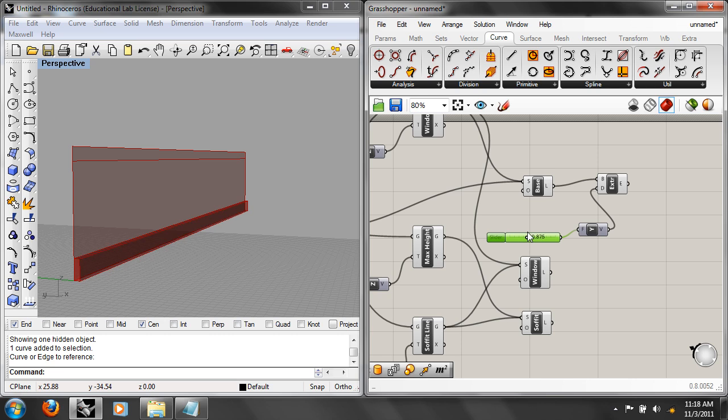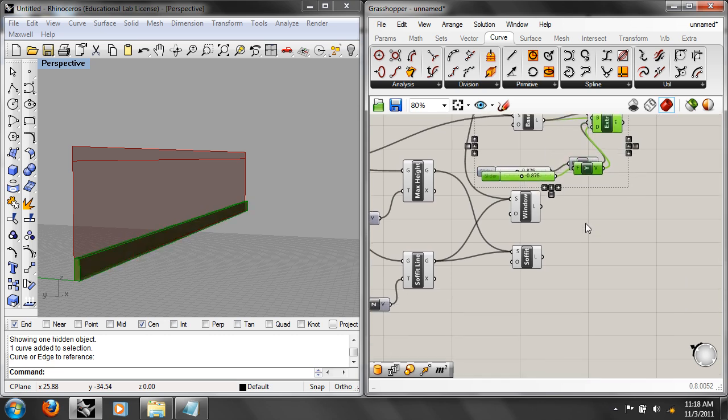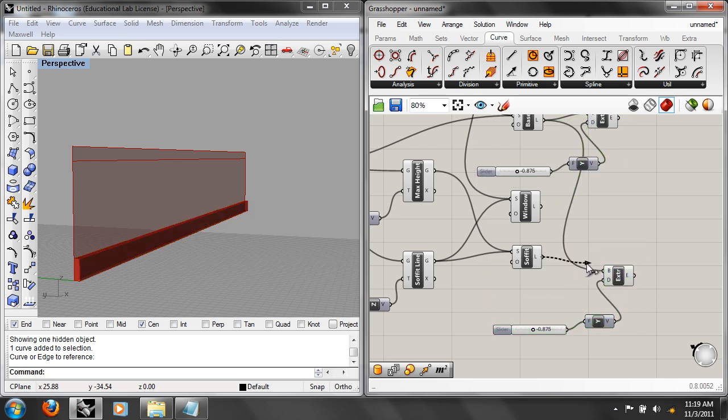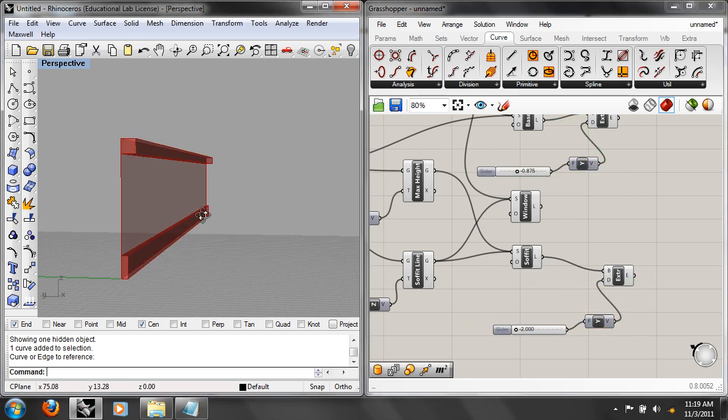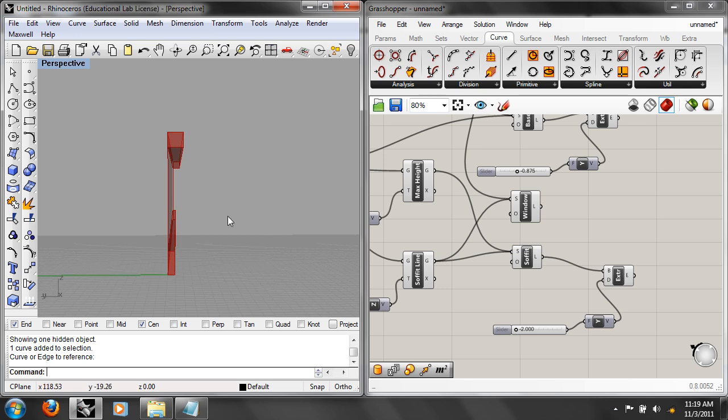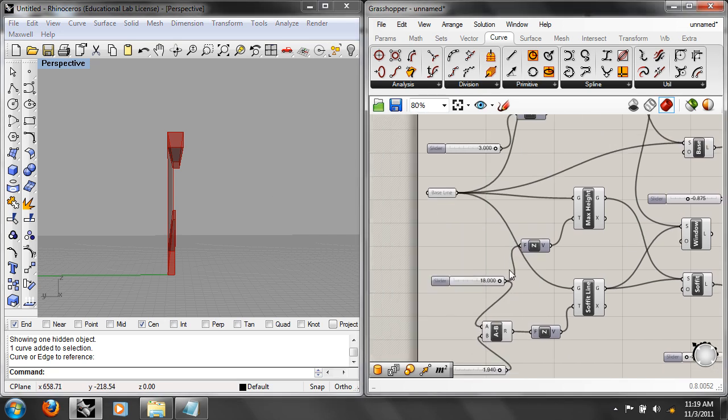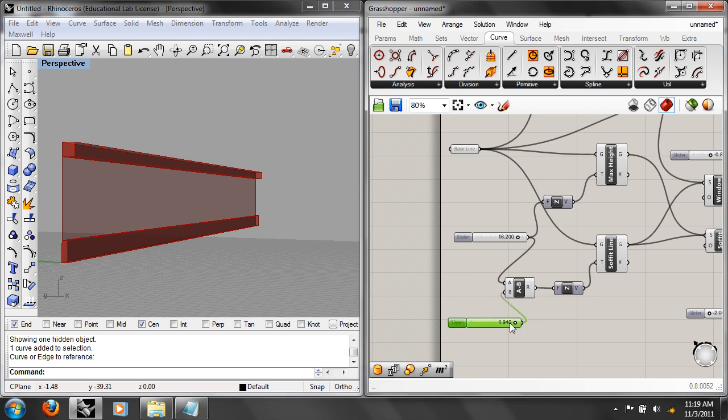And you can do the exact same thing. Like I can take this, copy it, and apply it to my soffit as well. So now I can make that even wider if I want to. You could do another extrude and then extrude it in positive, and then you get the other side of that window. So you might have a different thickness on the inside than you do on the outside, which probably makes a lot of sense. Okay, so you can see how that section is starting to actually take shape. And again, if I change the height of these different things, it's fully parametric.